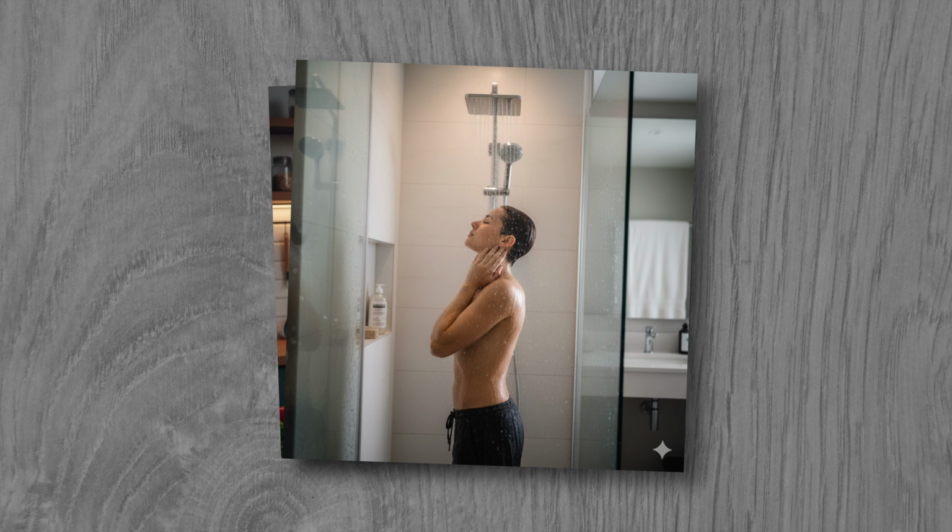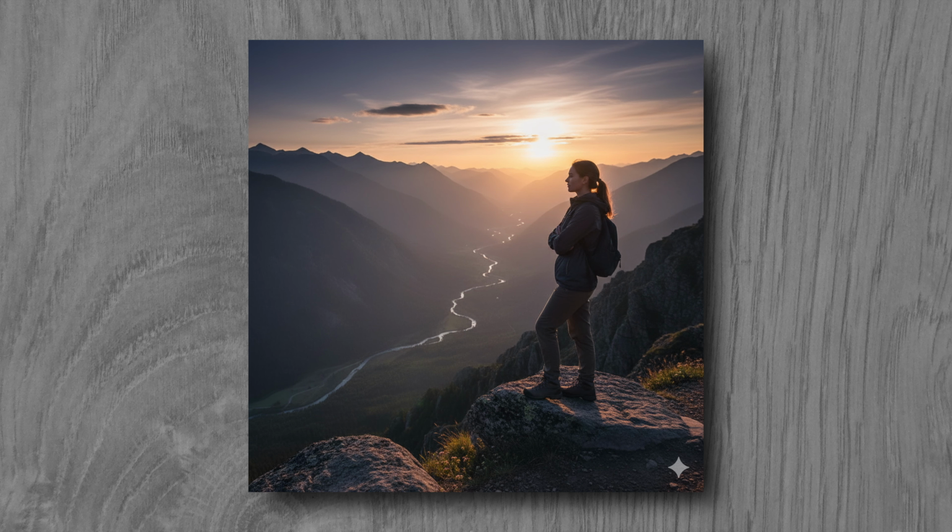Modern lifestyles contribute to higher humidity levels. Everyday activities such as cooking, showering, laundry, and even breathing release moisture into the air. Since modern buildings are better sealed, this moisture remains trapped inside, increasing the relative humidity and the potential for condensation on cooler surfaces.